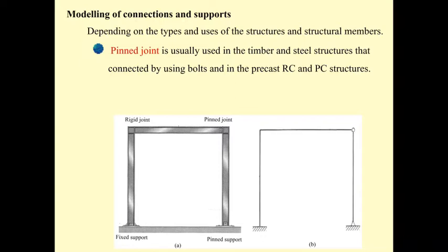And when you decide, in the final stage of design, you have to detail those joints and supports in accordance with your assumption. Mostly, if you model the support as a pin support, it will not have much constraint, okay, like this, compared to the fixed support that you are going to fix like this.